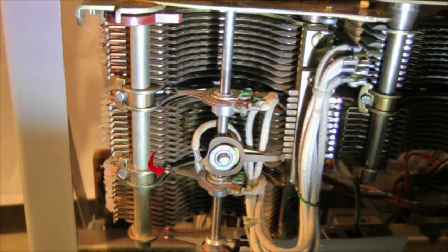The middle wiper assembly can connect to all 100 tip and ring terminals for line circuits 100 to 199, which are on the middle bank tier. The top wiper assembly can connect to all 200 sleeve terminals for line circuits 00 through to 199, which are on the upper bank tier.